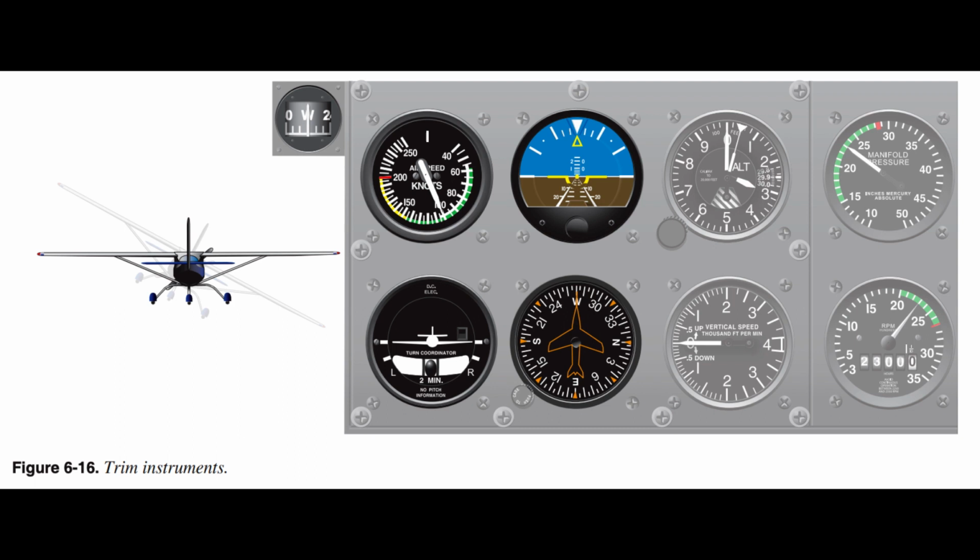In visual flight, a level attitude can be maintained by outside references. However, even then the altimeter must be checked to determine if altitude is being maintained. Due to human error, instrument error, and airplane performance differences in various atmospheric and loading conditions, it is impossible to establish an attitude and have performance remain constant for a long period of time.